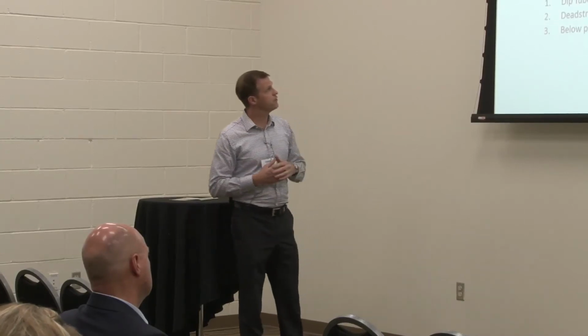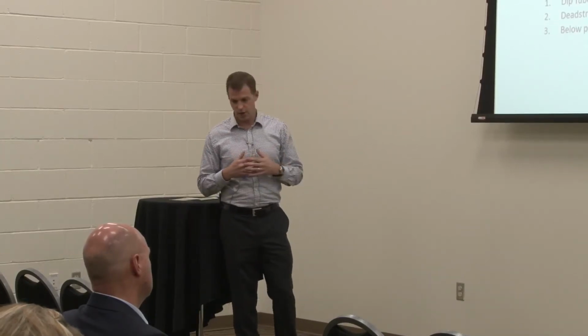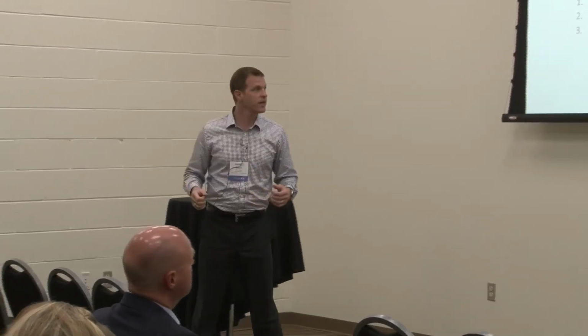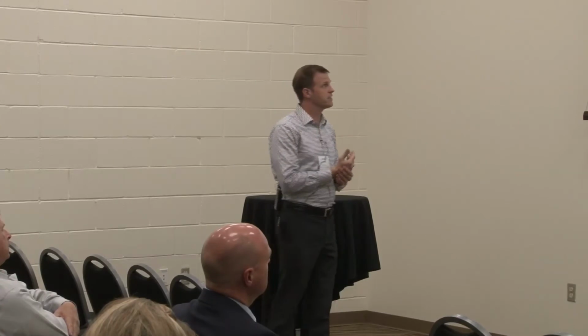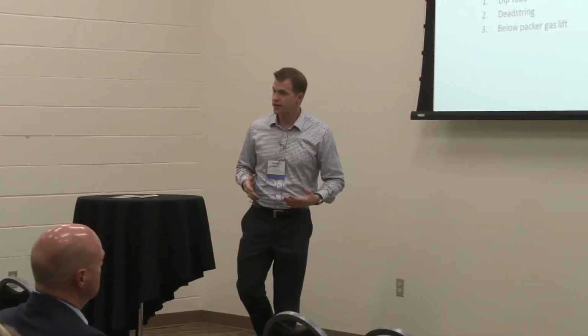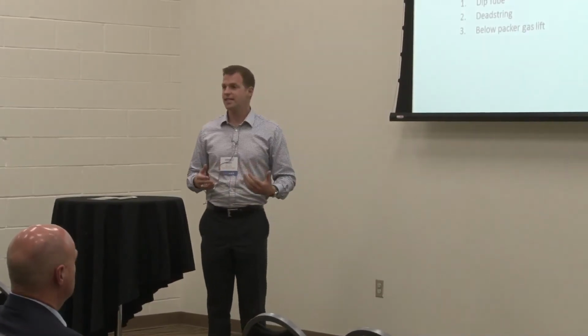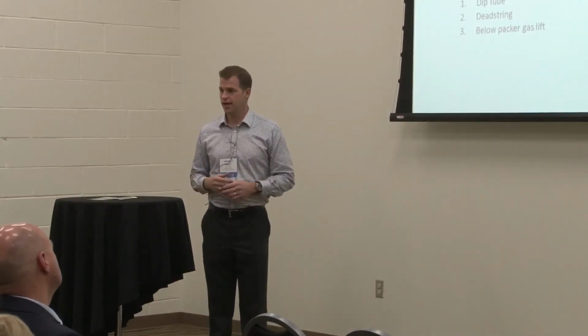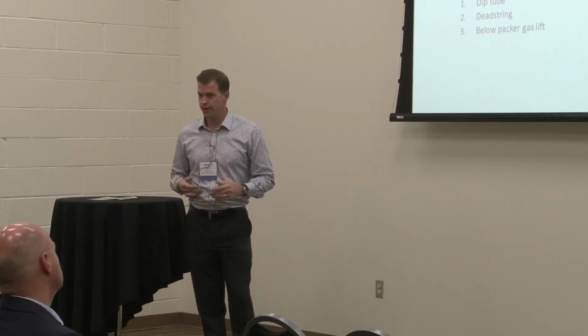And some of the things we use to determine if a redesign is necessary is a flowing pressure temperature survey. Fantastic for determining flowing bottom hole pressure, identifying injection points, giving us details as to how to redesign the gas lift system to increase production.